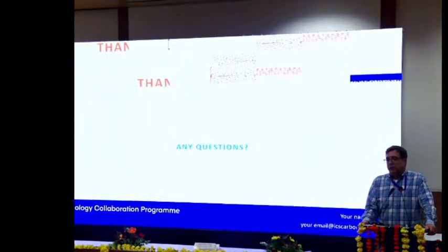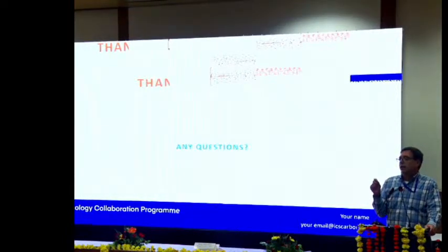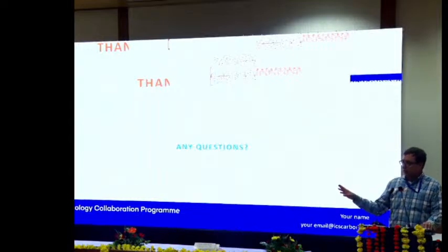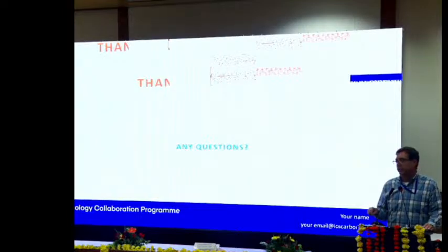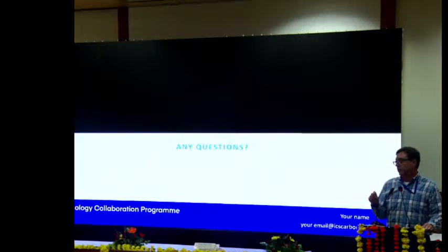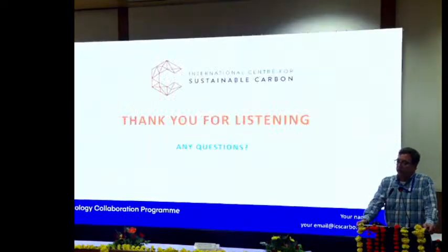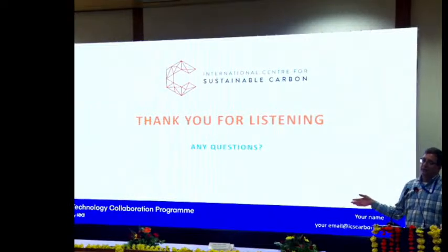So your questions regarding offline calibrations? Under Part 75, which is largely what I've been speaking to, we are required to conduct all calibrations while the unit is combusting fuel. It does not necessarily have to be generating power, but there has to be a fire in the boiler, and you want it to be somewhat normal operation. You can perform a calibration when you are offline, right?